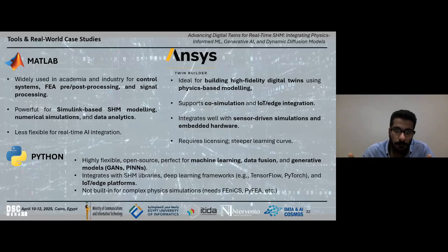So I have a finite element model and scenarios, and I apply the reduced space model to truncate the stiffness matrix, for example, to be able to solve the system very quickly. And then with the help of machine learning, you can identify which is pre-trained on the data coming from the finite element modeling.